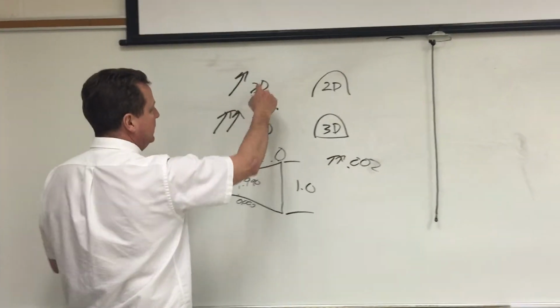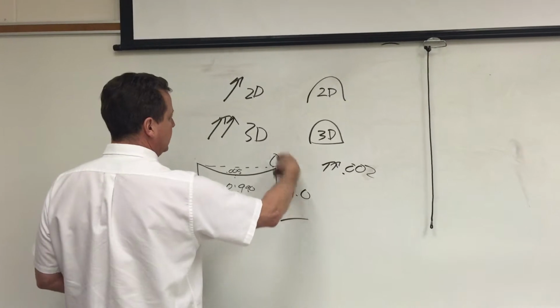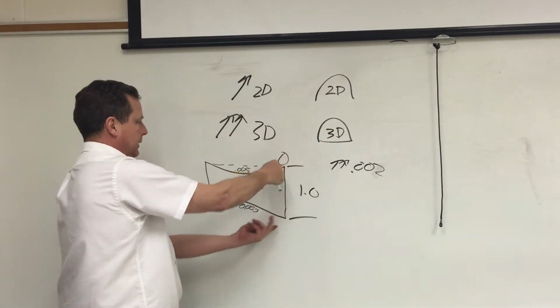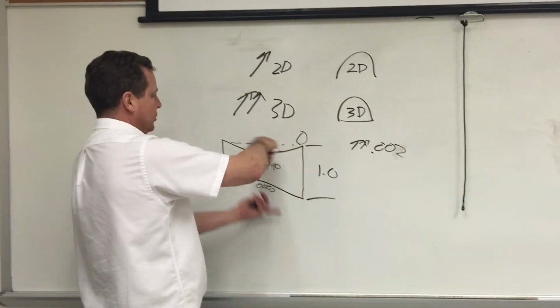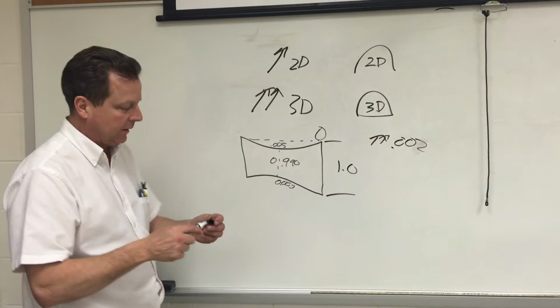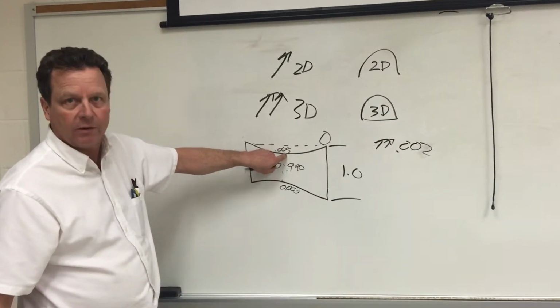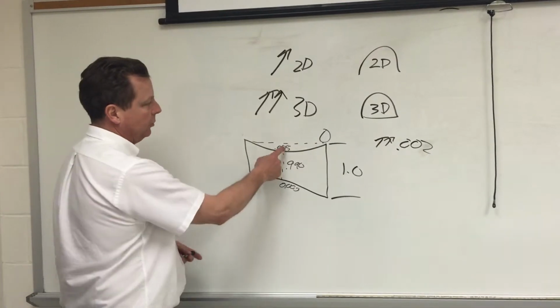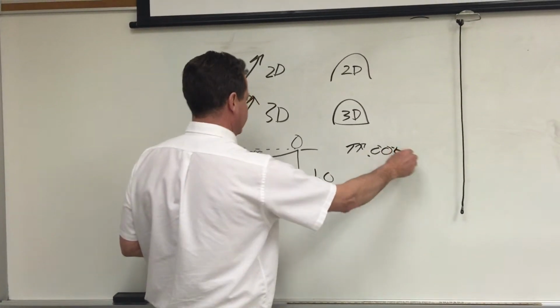So you can see if we had a runout of 0 here on this end, that's 2D. If we have to take in the entire surface and any deviations in the surface along that area, then we lose, and then we have to add that to the paperwork for total runout. The total runout of this piece is going to be 5 thousandths, not 2.